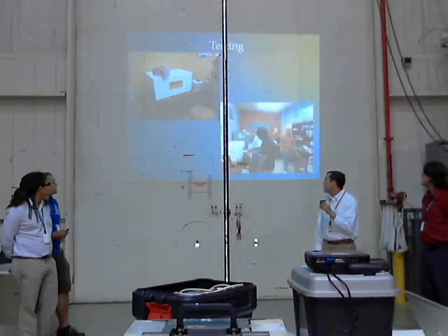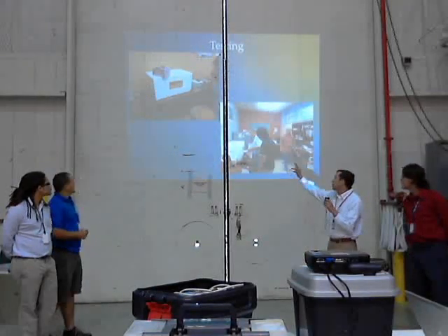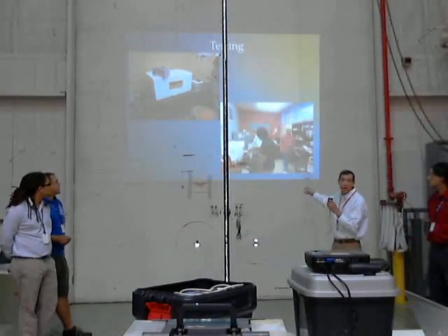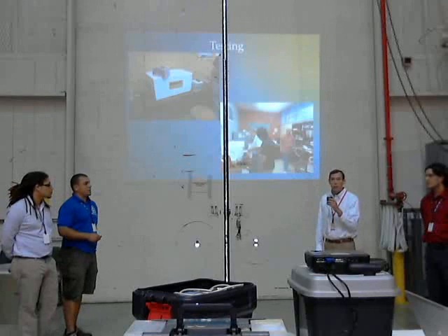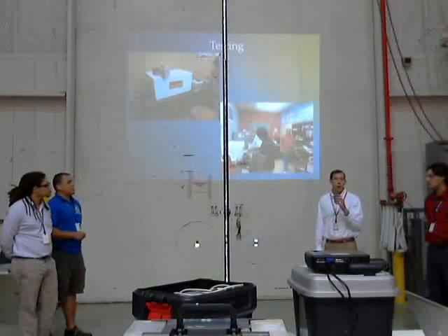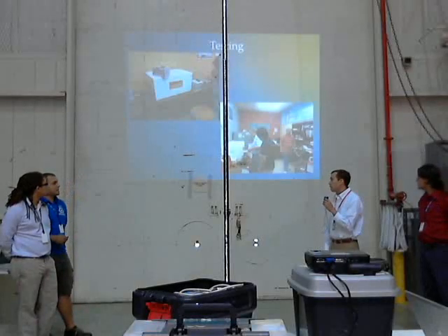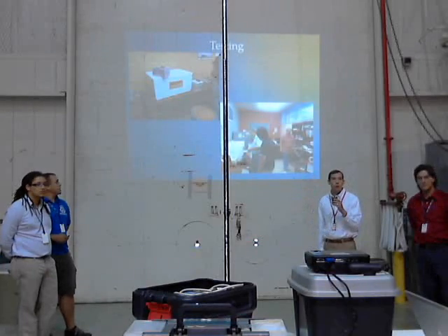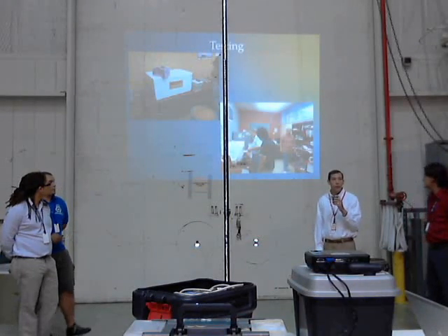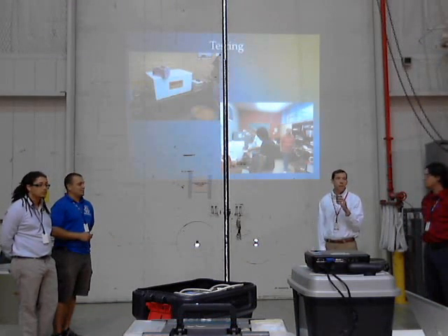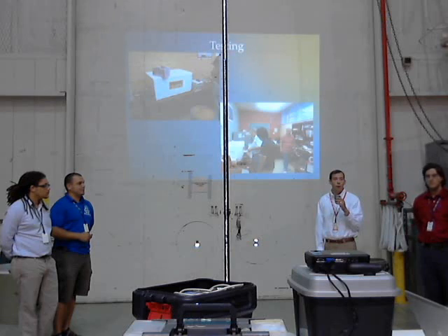Next, we went on to testing. We have our cold testing inside the payload, as well as cold testing on the sensor, since they will be outside in the elements. We even froze them down with frost and got less than 10% discrepancy in voltage. We also did spin tests in order to determine what signals we will get as the payload is spinning, as well as a hot test, and also a drop test in order to make sure that the payload will survive a 1-story drop.